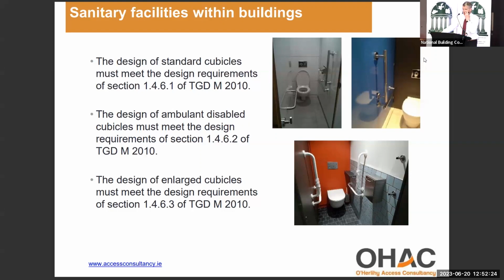And just one practical example, where we were working on student accommodation, and there were 2 accessible bedrooms located side by side. We went in to do an inspection, and the subcontractor was installing the grab rails in both of the accessible WCs and shower rooms. He was going into the first toilet and measuring where the grab rails were positioned. He was walking into the next one, and he was fitting the grab rails in line with the first toilet he'd done. The problem was the first toilet was incorrect. So he's basically doubling up on his previous mistake.